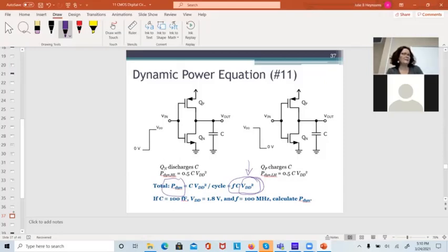Instantly free. You had to lower the threshold voltages on those transistors, which meant you made smaller transistors. So they've been taking this to the logical conclusion. Now it's 3.3, 1.8, 1.2, 0.8 volt logic, and it keeps going down every time.